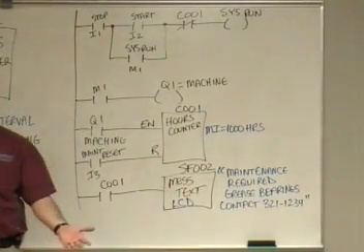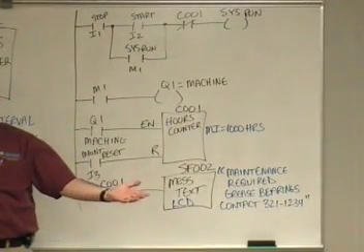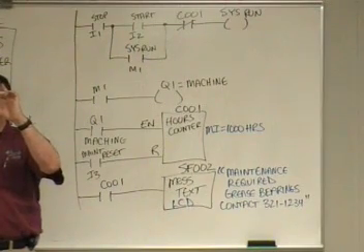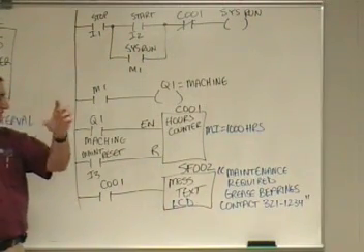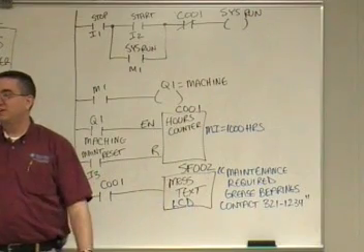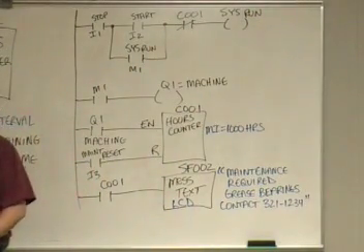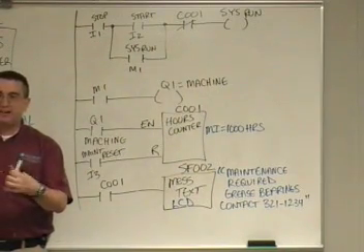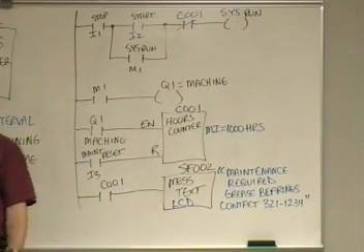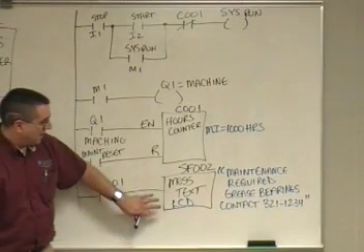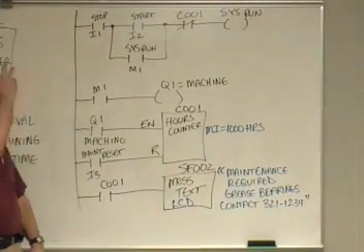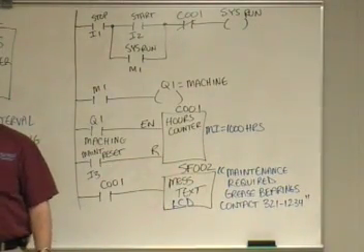The technician's going to walk up to the machine and say, "Why aren't you running?" And the LOGO! is going to display on the screen, "Maintenance required, grease bearings, contact this phone number." Now that operator can walk up to the phone and contact that number. The maintenance guy comes down, takes his little grease gun, and greases those bearings real quick. And now he hits the key switch, and the operator can fire the machine up again.